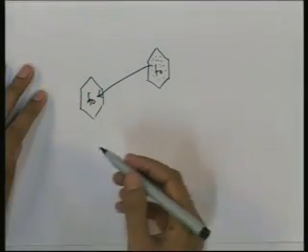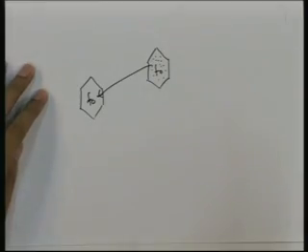just like we talked about the crosstalk in telephone, there is a similar problem in wireless too. It is not really exactly the same, but this is called the near far problem. Suppose now you have two different mobiles using the same band in the TDMA mode. We will discuss what is TDMA briefly in a moment, but suppose they are using the same frequency at the same time using different codes, so that their signals still don't interfere with each other much. There is some very minor interference.